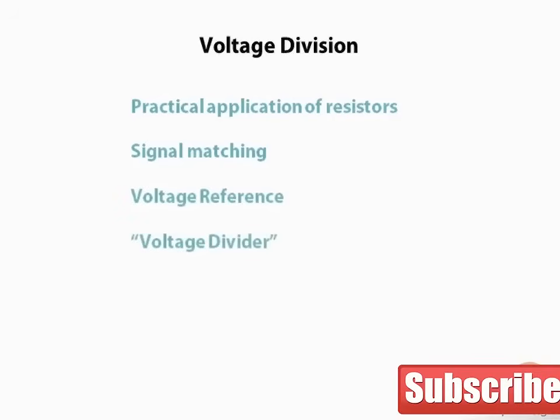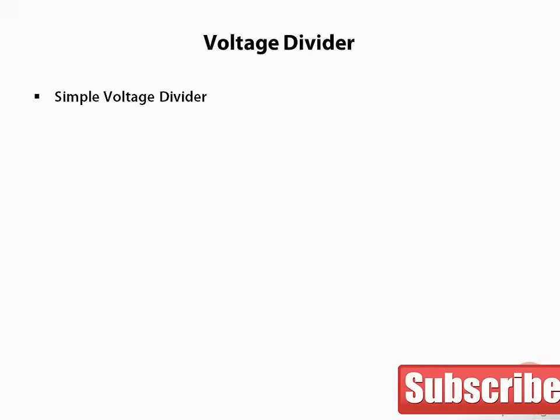The circuit we are going to analyze is called a voltage divider. We'll take a look at the circuit and then do a demo to illustrate its use. A voltage divider, in its simplest form, consists of 2 resistors connected in series, one end connected to ground, and the other end connected to a voltage. We can see this in the following circuit diagram.